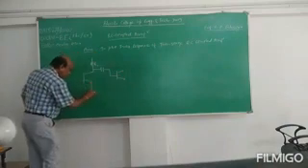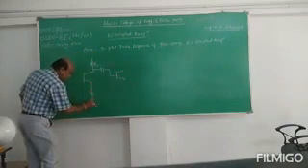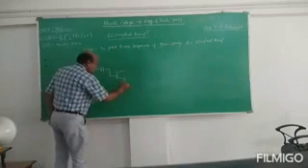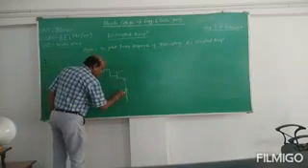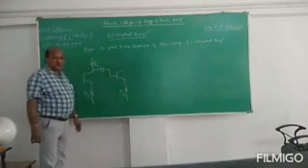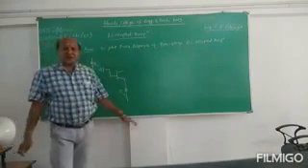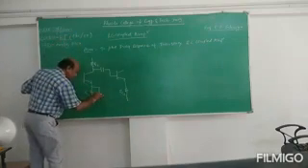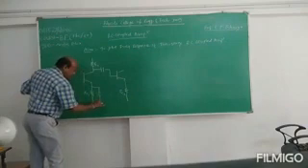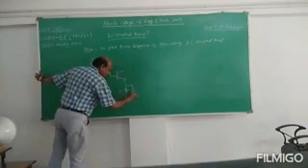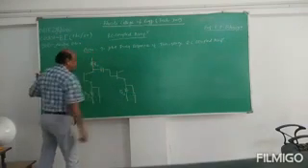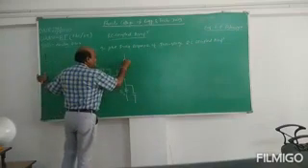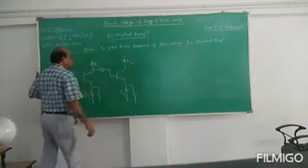Now you can have the emitter resistances: this one is RE1 and this one is RE2. Since we want to go for the frequency response, we will put a bypass capacitor across both these emitters. Here the bypass capacitor is used, and similarly here the bypass capacitor can be connected. Here the resistance at collector 2 is used, that is RC2.